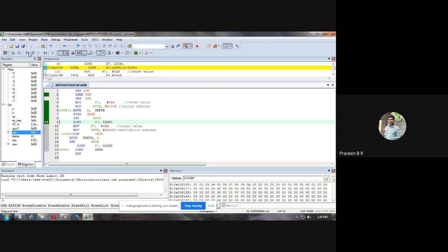So like this, 10 datas are going to get incremented. How do you know? Every time when it is incrementing, the register R7 keeps on decrementing. The data present in R7 keeps on decrementing. So it is moving from external memory location to the stack. So you can observe at one point of time, R7 will become 01. The data that you are moving from the data pointer 8109, that is 0A, will come to accumulator now. This is the last data. From that, it will go to the stack. Your stack will get incremented to the next number 11.